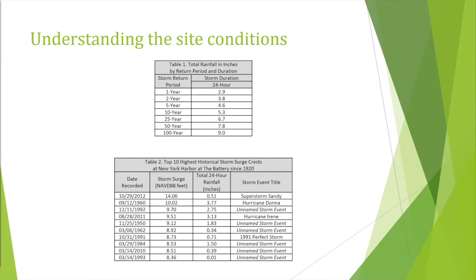Obviously, the Coney Island Complex in Brooklyn is their largest rail yard. Every train goes in and out of there, whether it's for maintenance, for washing, things like that. It's over 100 acres. It's right next to Coney Island Creek. So they were very adamant: we want you to protect us to a Category 3 hurricane plus 3 feet of freeboard, and then we have a nice bathtub. And then we want you guys to design a stormwater management system that will deal with a 100-year rainfall event. And we're like, are you sure you want that whole combination? And they were like, yes, that's what we want. We never want another Sandy to happen to us again.